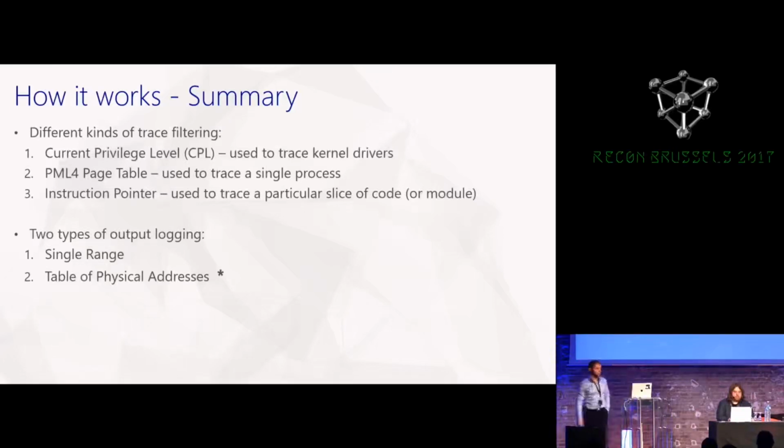Otherwise, the last filtering mode is by instruction pointer. You can set a start point and an end point, and ask the processor trace to trace only that window of code. And this is very cool.